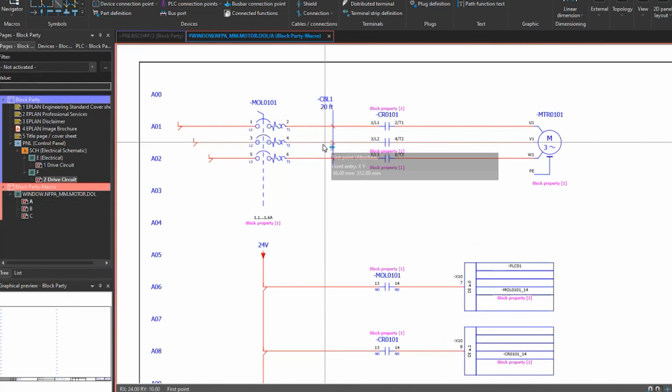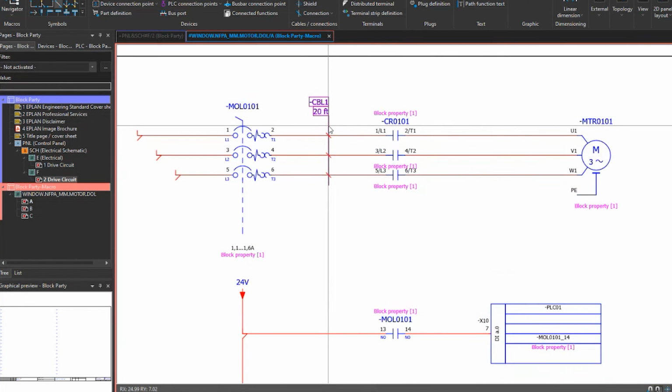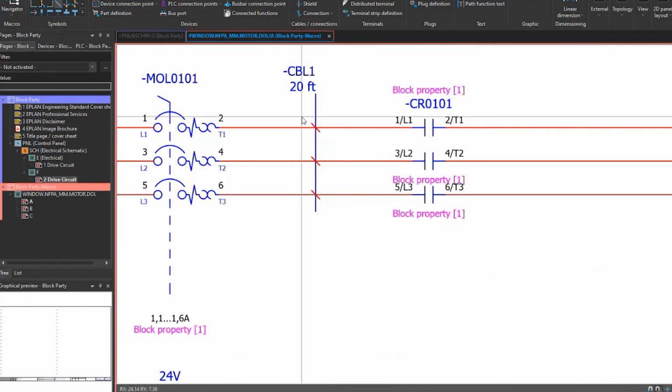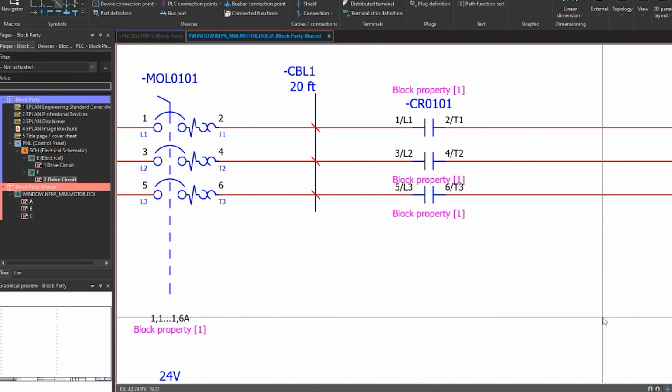And you could define the block property to look for the voltage drop, right? V equals IR. So I can use that formula to determine the drop, depending on the length of the cable, right? You would need some sort of knowledge about the resistance along the way, and the current and all that.